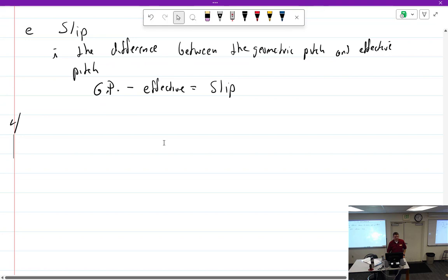I know we haven't talked much about constant speeds yet, but I'm in a constant speed propeller, at the end of the runway, with my feet on the brakes, and I go wide open throttle. What am I going to see RPM wise? Nothing. Red line's going to be red line. It better be red line. Should go right up to red line.